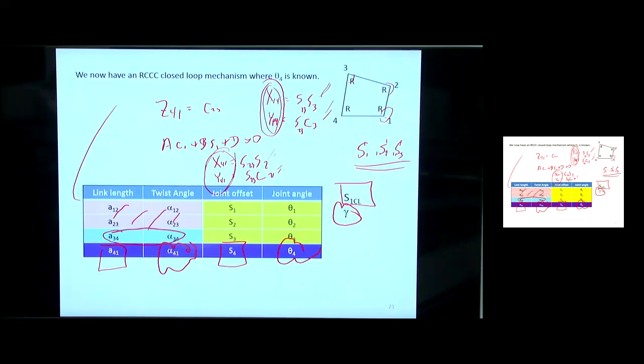Well, I'm going to go ahead and write the vector loop equation. And there's only 8 terms because it's a 4-bar, right? There's 4 of the S vectors, and, again, engineering essay question, because I know all the angles for the A and the B case, I can evaluate all 8 of those vectors in a common coordinate system for the A case and solve 3 equations in these 3 unknowns. And then evaluate all those vectors for the B angles.